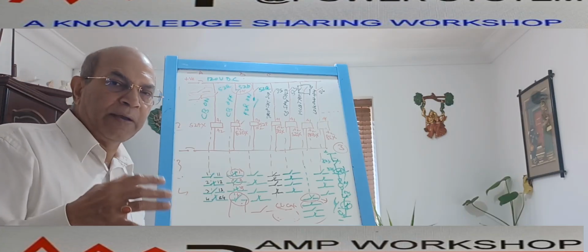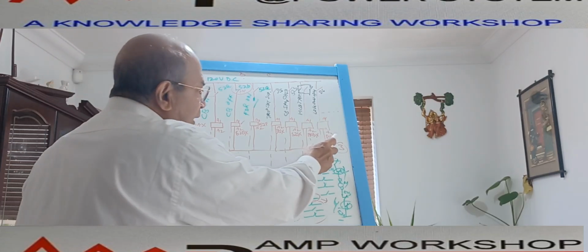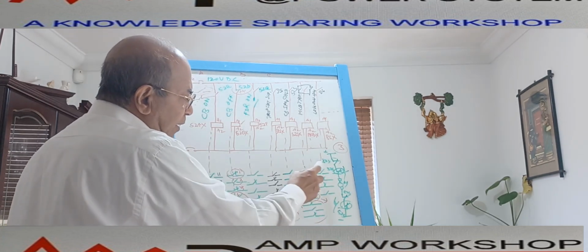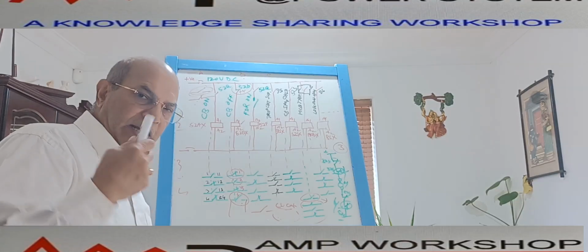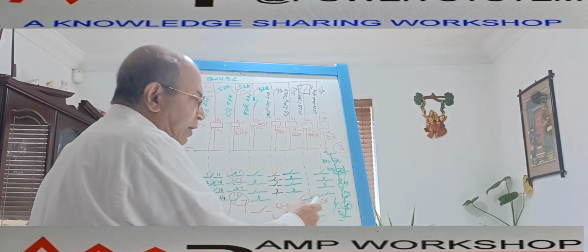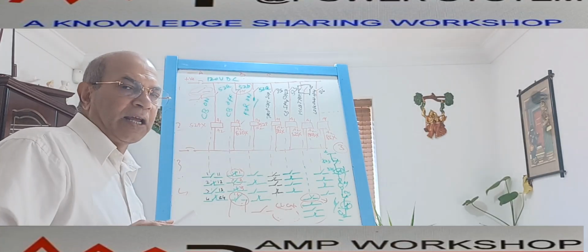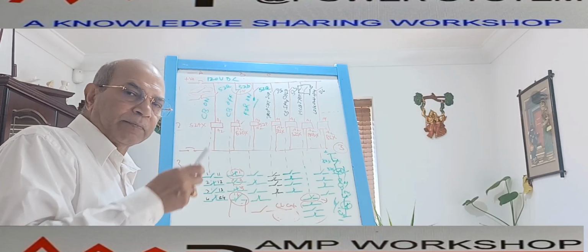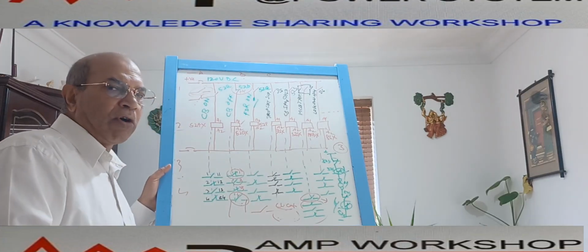In that case, we use another multiplication contact of an auxiliary relay. This auxiliary relay is an 82X relay. Similarly, it has multiple contacts. The contact configuration and the current rating of the contact we can choose based on the relay. We can select a relay which might have 8 contacts and a contact rating of 10 ampere. If such a 10 ampere auxiliary relay is not available, we sometimes use a contactor so that the required current rating auxiliary contact is available. So that way, based on the requirement, we can use the auxiliary relays.